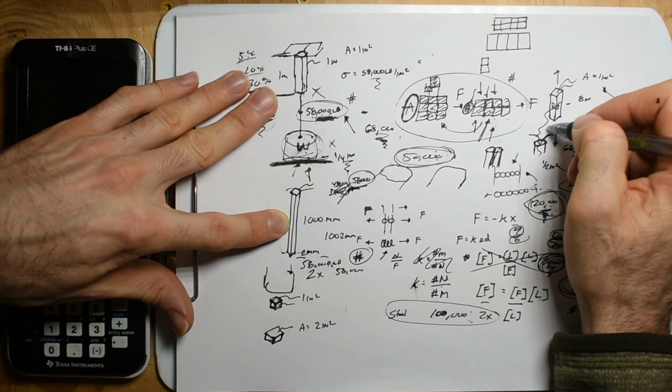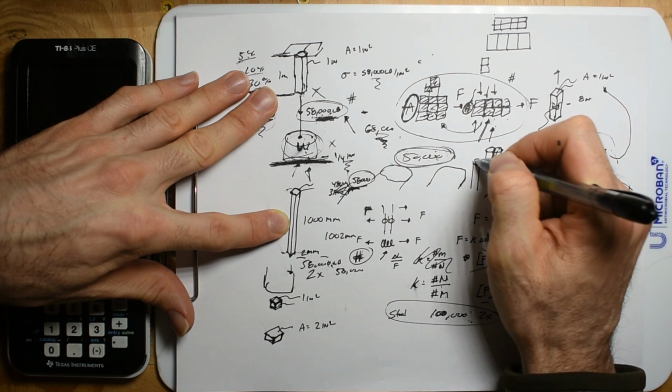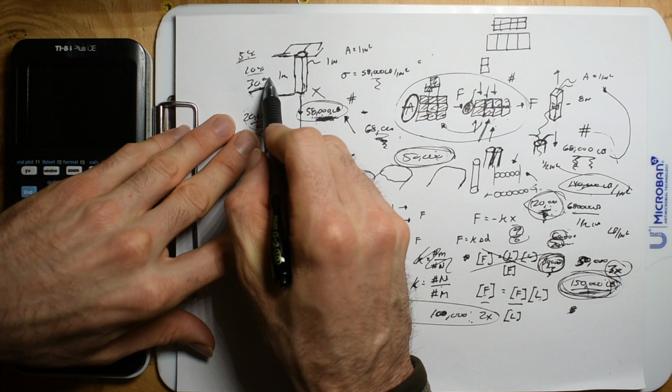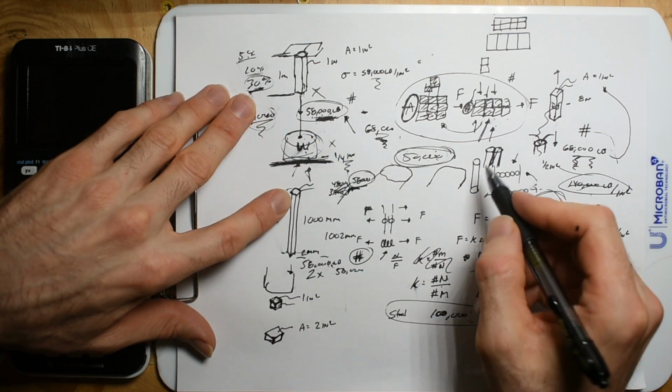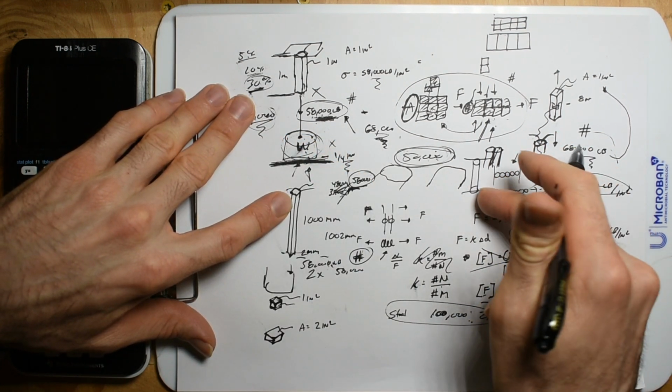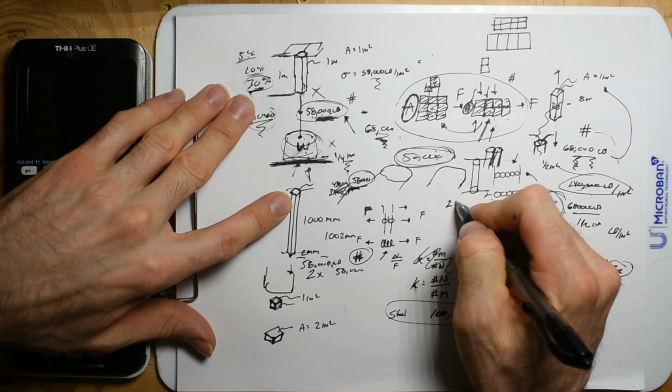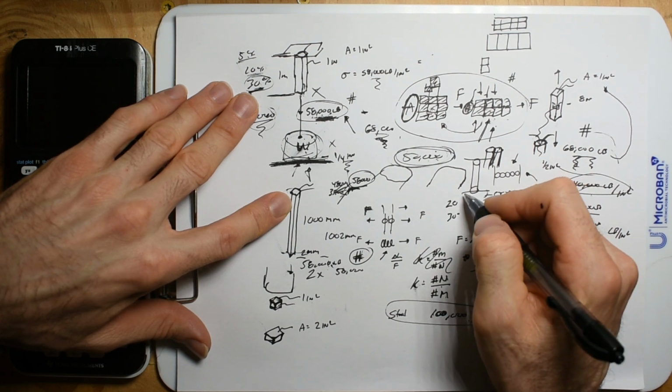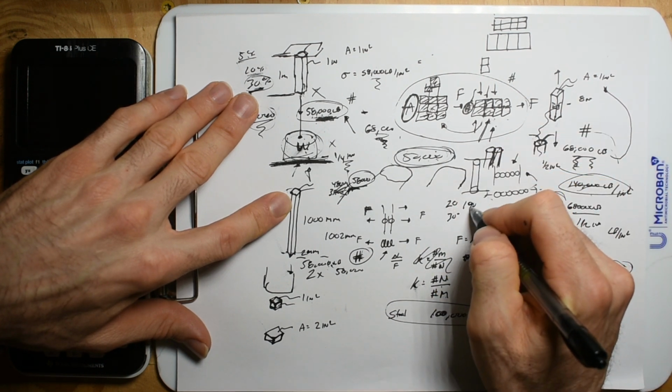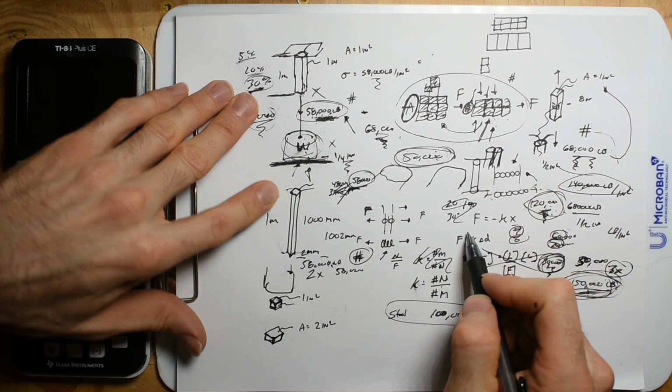So if I do take that steel that's all stretched out, that's already 20, 30% stretched, and then start with that, I can't stretch that another 20 to 30%. I can stretch that hardly any, maybe hardly less than 1%. So keep that in mind.